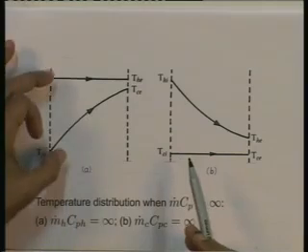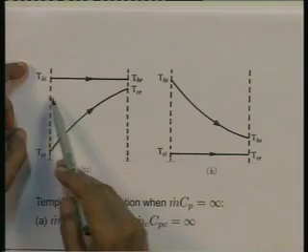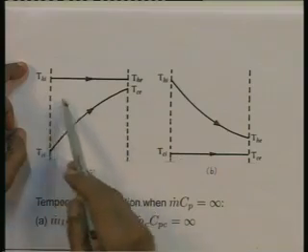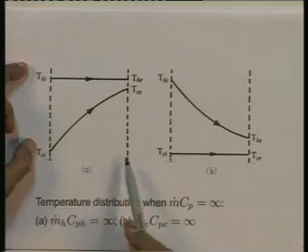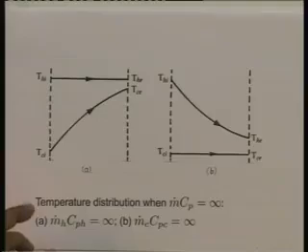The way I have shown it, it is parallel flow, but remember, even if it is counter flow, all that will happen is I will get a mirror image kind of variation of T c in the other direction, and therefore, you can see why the mean temperature difference is the same whether it is counter flow, cross flow or parallel flow. So, these are the two special cases. Now, let us do a couple of problems to illustrate all these ideas of mean temperature difference for different flow arrangements. Let us take one example.